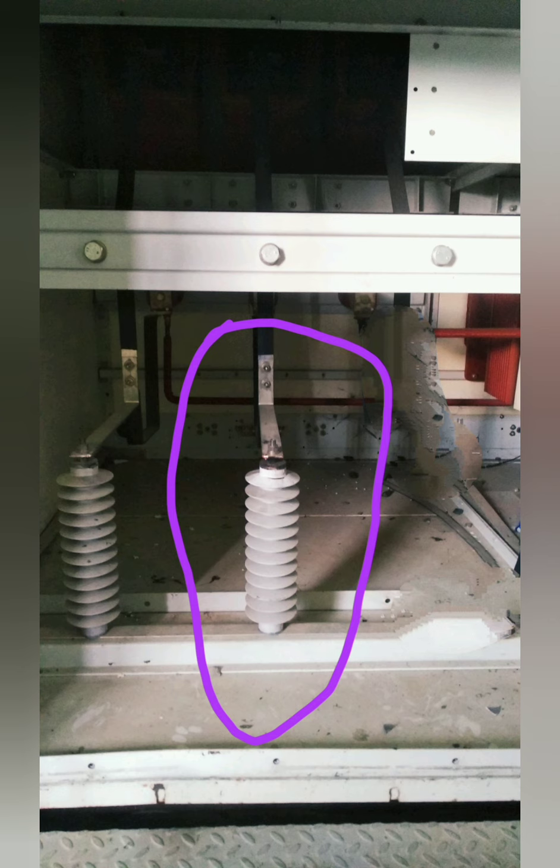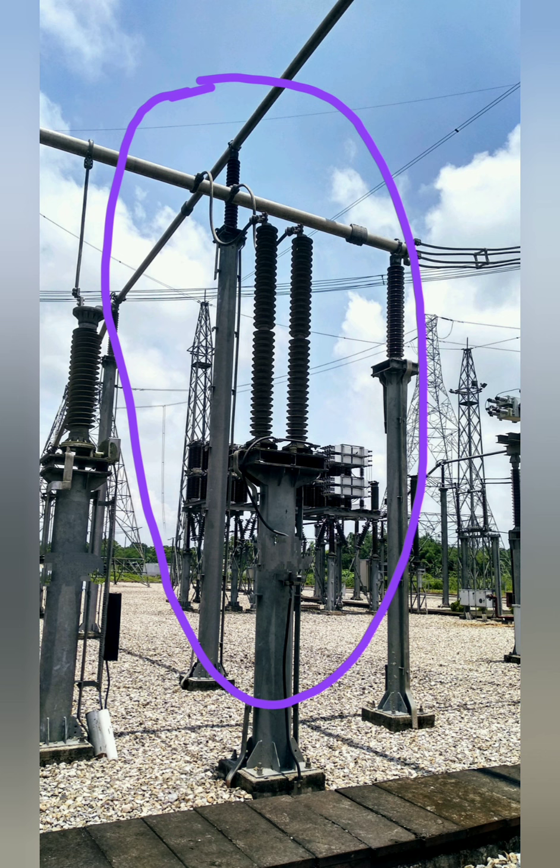Here the lightning arrestor is connected in parallel with your earth. Then this is your HVDC yard neutral bus lightning arrestor. At the top you can see the neutral bus is connected with the lightning arrestor, and the lightning arrestor is further moved to your surge monitor. Then by the surge monitor there will be some indicating device connected, and it is moved to earth.